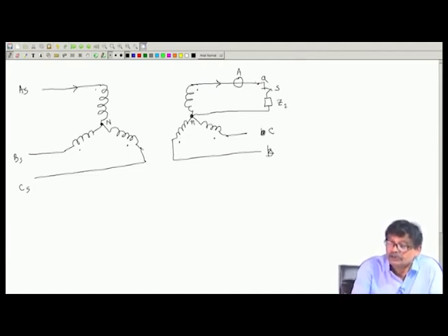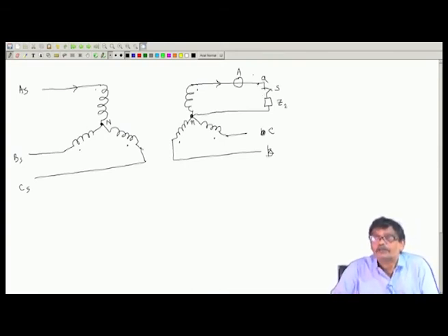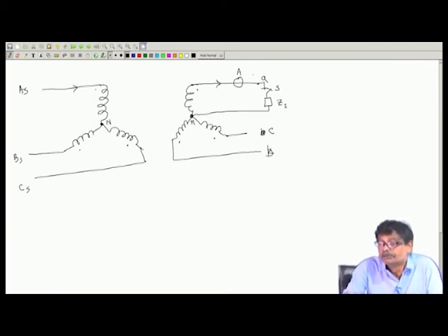after closing you find this current is very little or no current, then I must tell that if very little current, then the voltage V A n must have been very small. Otherwise, how? That is how Ohm's law is also satisfied. In other words, what happens is this: the moment you try to put a single phase load, this neutral will oscillate. Situation will be like this.